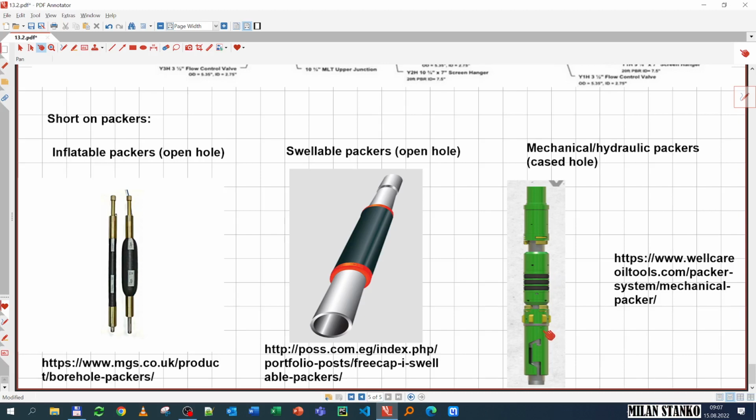Again, it's a bit complicated how it is done, but you essentially have to compress from the top and from the bottom, and for that you typically use these slips that essentially bite into the wall and are fixed. You fix one part in place, then you squeeze, and then you fix the other part in place, such that this sticks out and then it becomes activated.